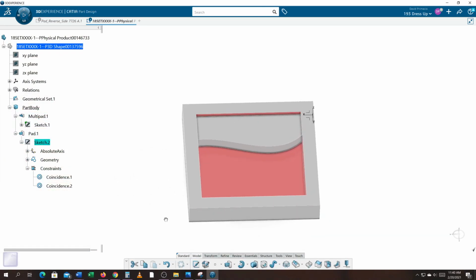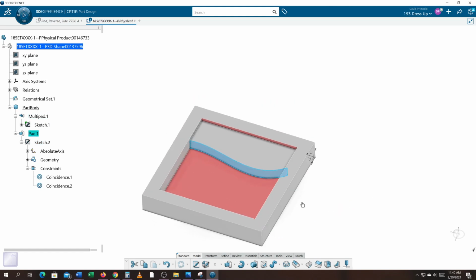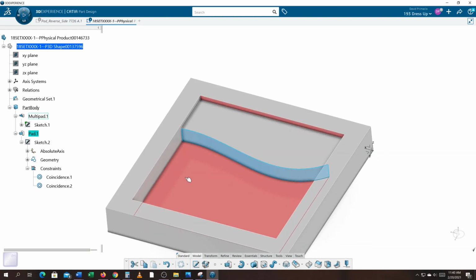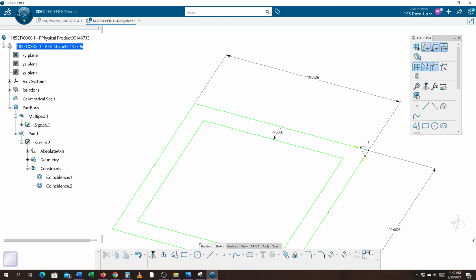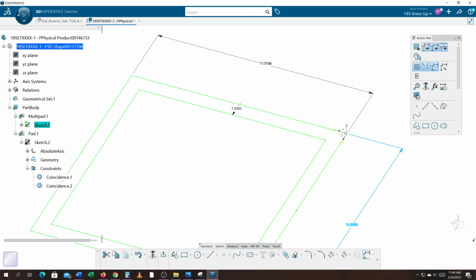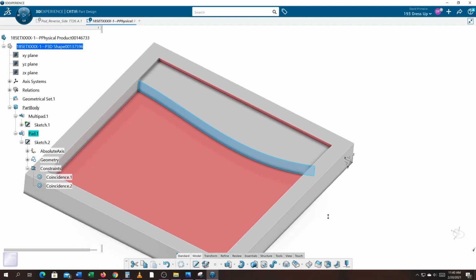And what's going to happen different is, first off, you'll see I fixed that. No longer has that boundary edge there. If I change this, let's say 15, and I exit out, you notice on that surface here it stays nice and smooth and is able to stretch.